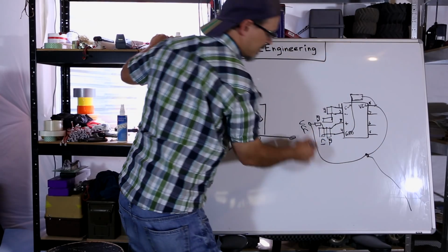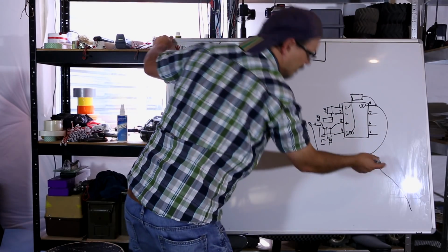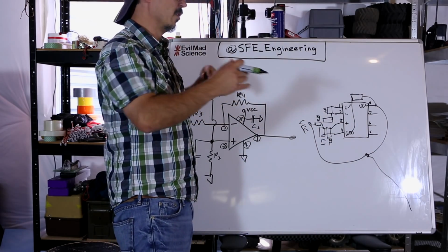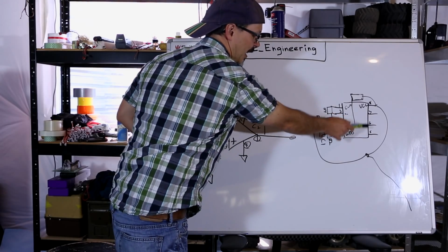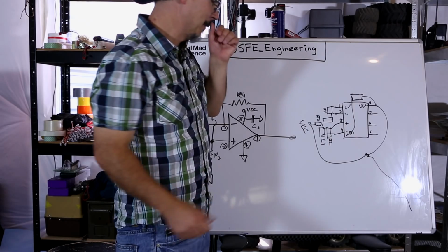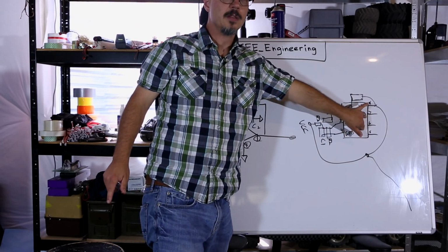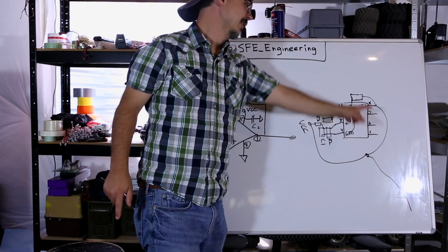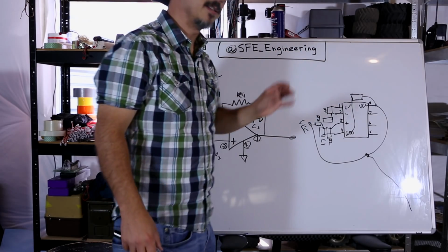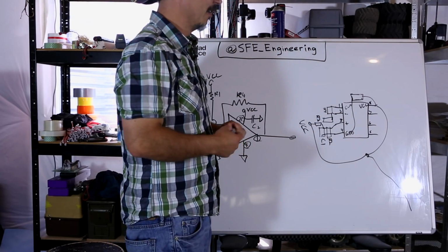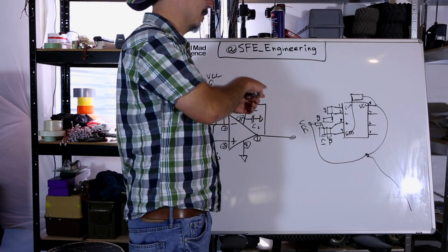So that these lengths are equal, and that way neither one of these things, if it starts to draw current, will cause noise for the other. This being an op amp, a 2 op amp package, you don't want to leave these pins floating, okay? This thing will oscillate like a thing that oscillates a lot. So what you're going to want to do is tie those lines.